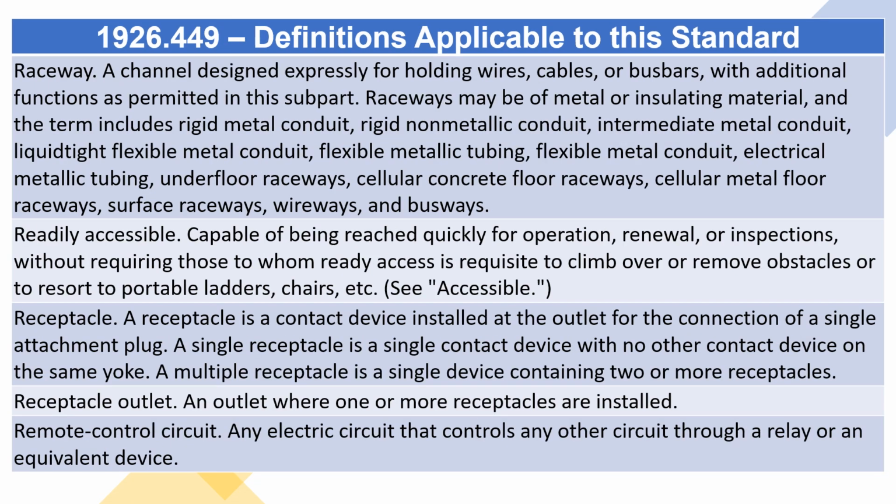Raceway. A channel designed expressly for holding wires, cables, or bus bars, with additional functions as permitted in this subpart. Raceways may be of metal or insulating material, and the term includes rigid metal conduit, rigid nonmetallic conduit, intermediate metal conduit, liquid-tight flexible metal conduit, flexible metallic tubing, flexible metal conduit, electrical metallic tubing, underfloor raceways, cellular concrete floor raceways, cellular metal floor raceways, surface raceways, wireways, and busways.